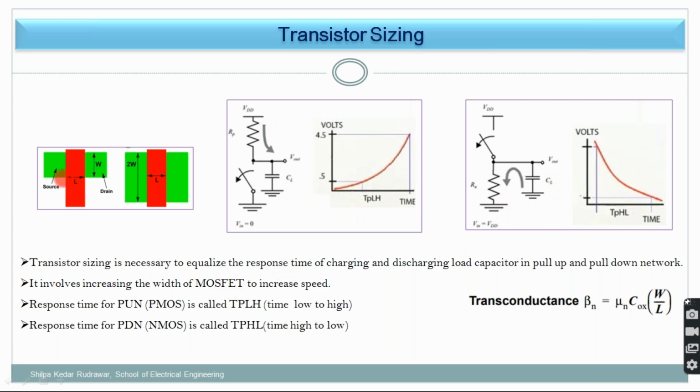You are able to see the diagram here, green, red. So this is the particular concept of microwind. You need to draw the transistor in this way. This red indicates polysilicon, which is forming the gate of the transistor, and this is W. This other color you are able to see is the diffusion, N plus or P plus diffusion, because doping forms the N regions or P regions in the transistor. So this is the doped region. Here it is the source, this is the drain, okay, and this is the gate. So these are the 3 terminals available.